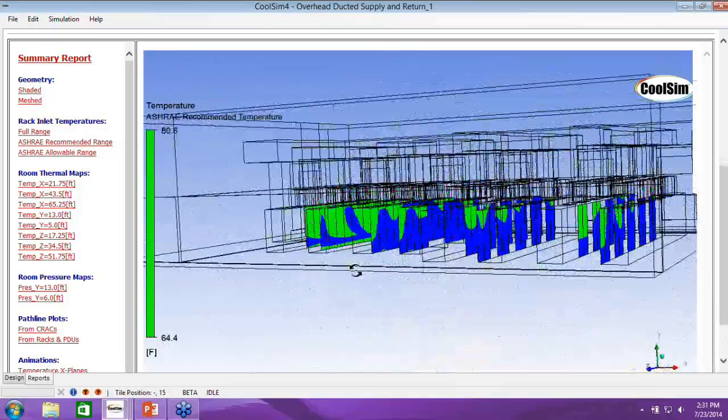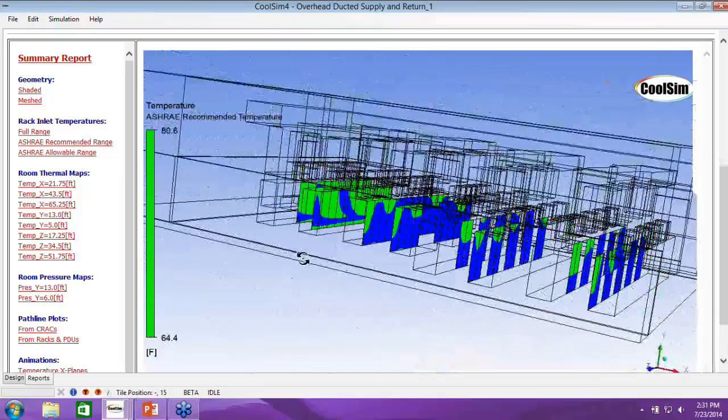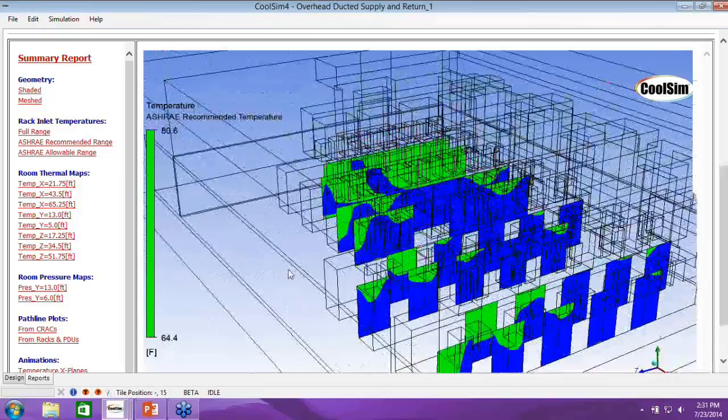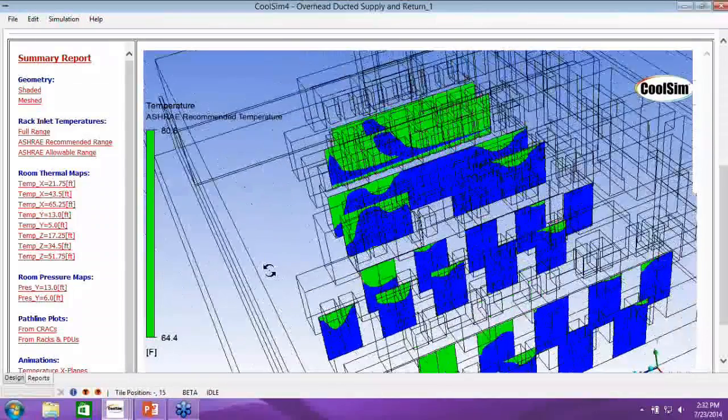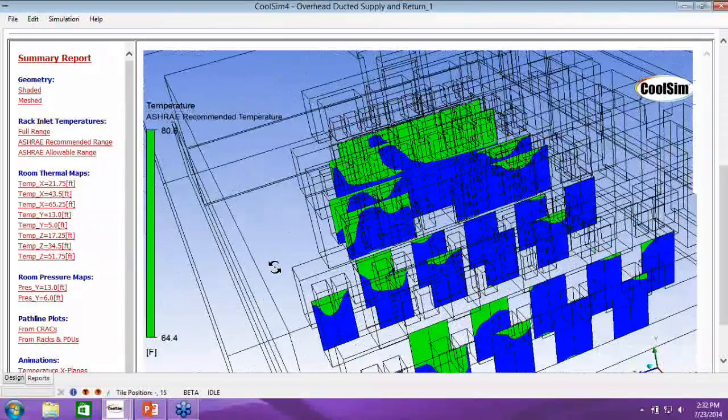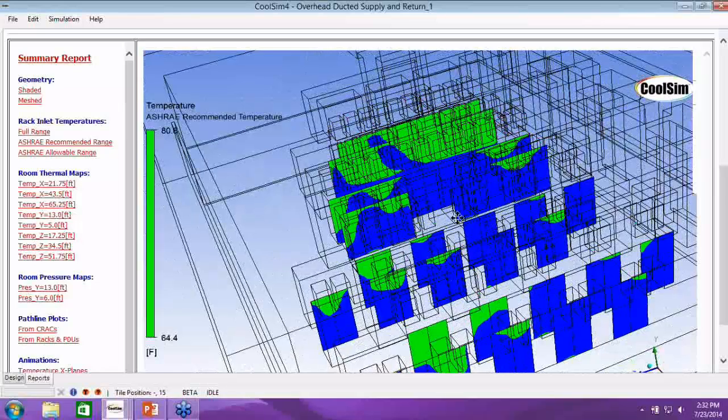So right here we can see that we're too cold. In most of that room, Magnus, we're too cold, right? Right. And there's two reasons for that. One, we got too much air, and two, we're running at too cold a temperature. But the contours themselves tell you something else about the room. That tells me that over here in this corner I've got trouble. That's going to be my problem spot over there because that's warmest compared to others, and a little bit over here.